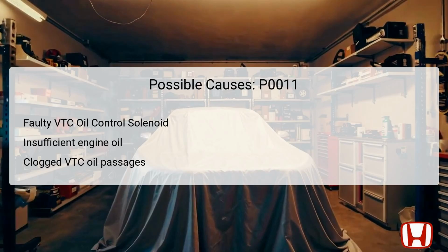The third common cause is clogged oil passages within the VTC system, which can restrict oil flow and disrupt timing adjustments. Recognizing these possibilities allows for focused troubleshooting efforts, simplifying the repair process and restoring proper engine functionality.